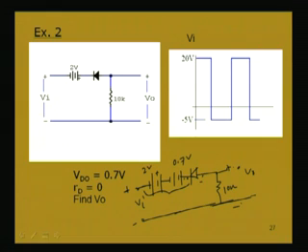So, this is higher at a negative. So, this will be reverse biasing, it will not be conducting. So, when it does not conduct, the voltage across this resistance will be 0, since no current flows. You have to be careful where you want to find out the voltage. Here it is across this resistance.